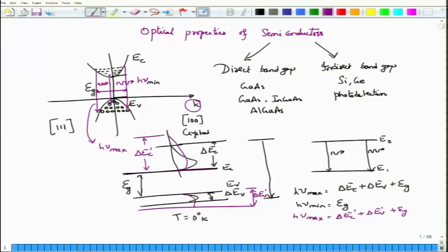Why should it increase? Of course, we know that this is all controlled by the temperature and the Fermi-Dirac statistics that is obeyed by the semiconductor. Because with increasing temperature, there is a lot of thermal energy available. So, the electrons can spread out and the holes can also spread below the valence band, thereby increasing the spread delta EC and delta EV, and thereby increasing the line width of the laser. Now, this is very crucial.